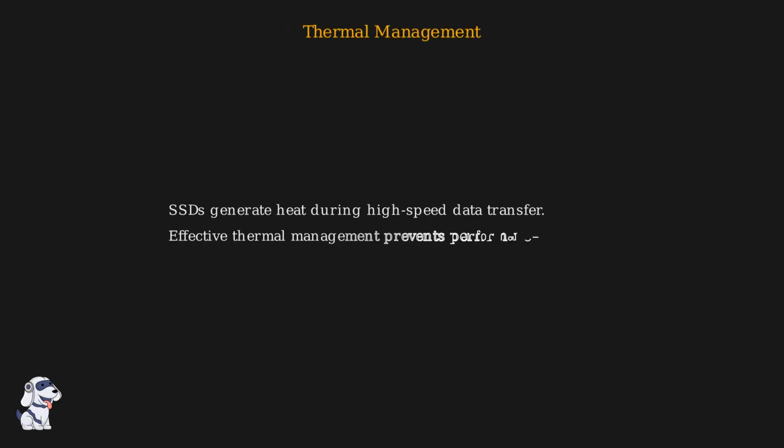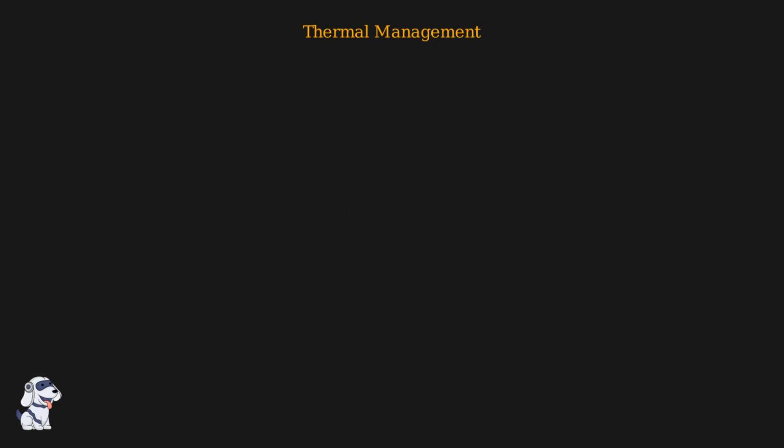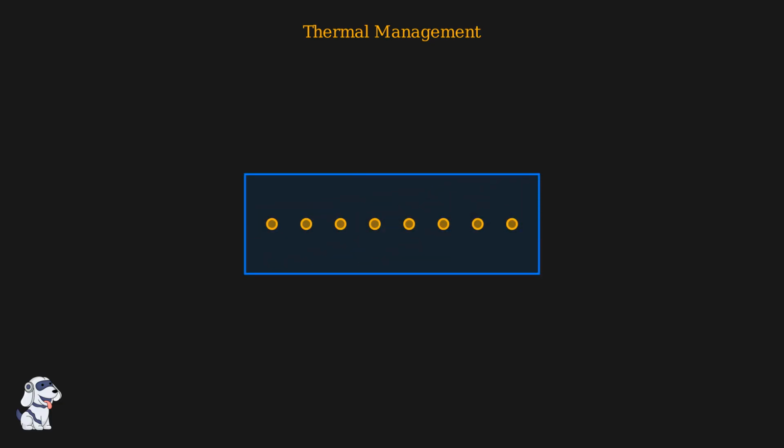Thermal management is a critical aspect of SSD design. High-speed data operations generate significant heat, which can lead to performance throttling if not dissipated efficiently. Components inside the SSD, specifically the controller and NAND flash, act as heat sources. During intensive tasks, the temperature rises significantly. Advanced thermal solutions like heat spreaders conduct heat away from these components, maintaining stable operational temperatures even under heavy load. In edge computing, SSDs face extreme environments, operating reliably from freezing -40 degrees to scorching 105 degrees Celsius.